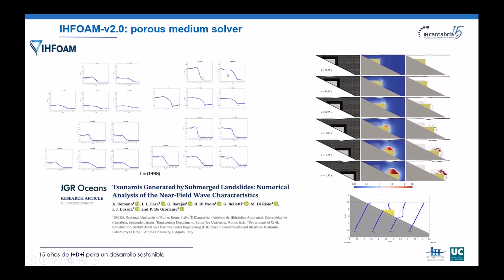So we extended the porous media solver to be able to work in the OVERSET framework. We know that when we have moving devices, we must have at least 4 cells between the moving or OVERSET device and one of the boundaries. The idea was to replicate this wall by a porous media, with a small permeability, so it didn't allow the water to go inside and it was acting like a wall. You can find this working on the website.